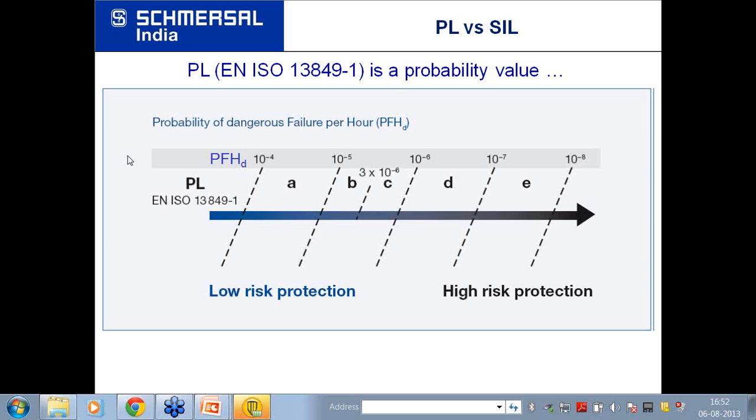Mr. Balaji Tilak has asked a question: how do machine startup safety and shutdown safety differ in SIL level? I don't think there's any difference in that as far as SIL level is concerned, because SIL level is a parameter of probability of failure or dangerous failure. So it all depends on that particular parameter. It doesn't matter whether it is a SIL or a PL, it doesn't matter.